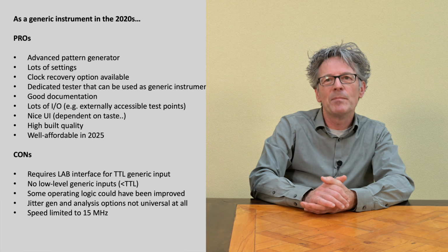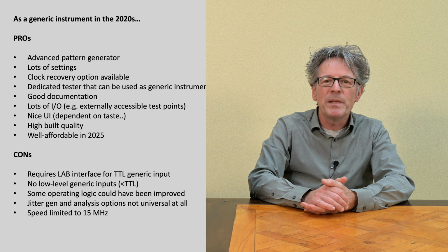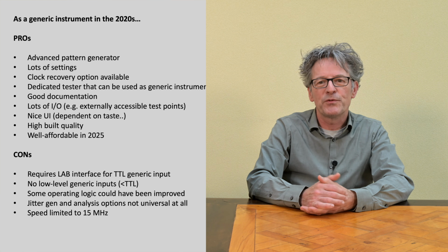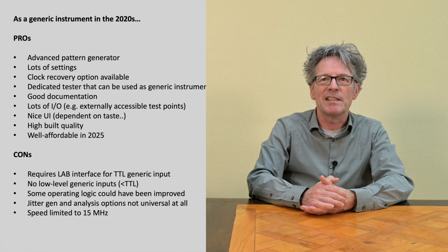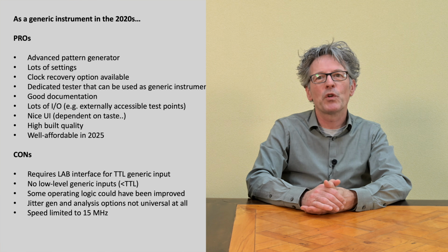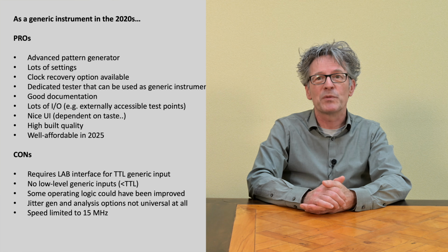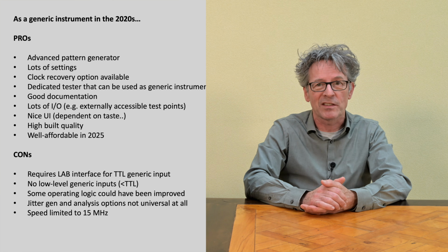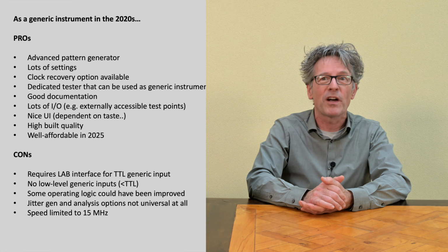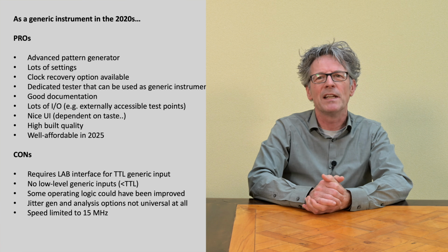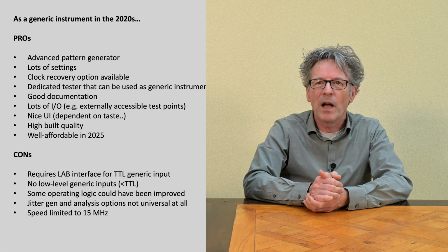And finally, a limitation might be that the speed of the device in terms of generating and analyzing signals is limited to 15, respectively 16 megahertz. It might be okay for your occasion, but if you really want very high rate bit streams for testing buses, etc., more going into eye diagrams or fast buses, then you probably need other equipment, but you're probably talking about an entirely different price range as well.